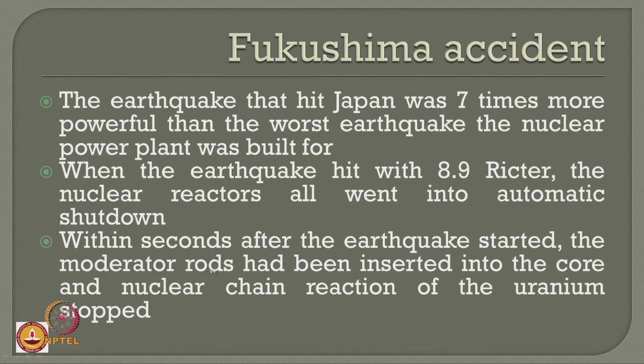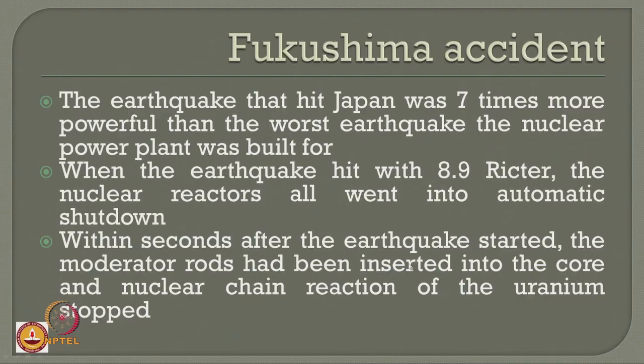Moderator rods will always attempt to kill the chain reaction and make the power plant cool down automatically, but cooling down of the plant is not instantaneous, it will take some time. So, within seconds after the earthquake, moderator rods were inserted into the core and the nuclear chain reaction of the uranium was stopped. One can say this is the first line of defense of safety by design.